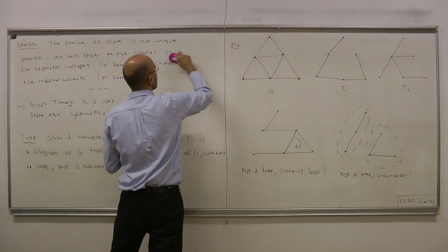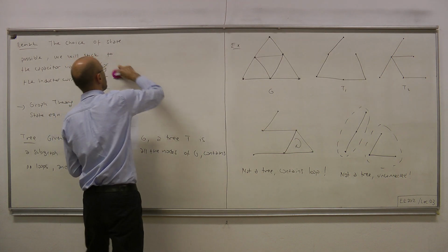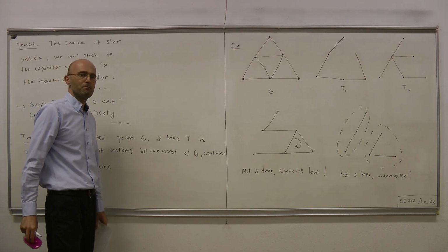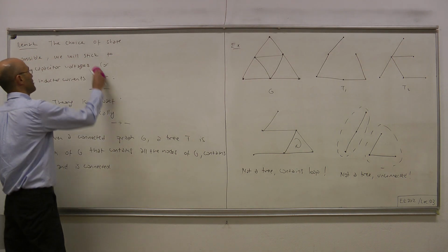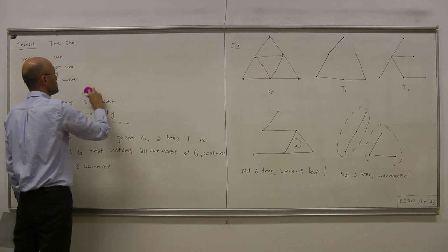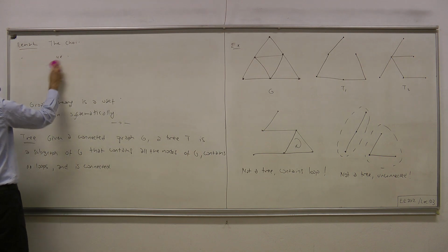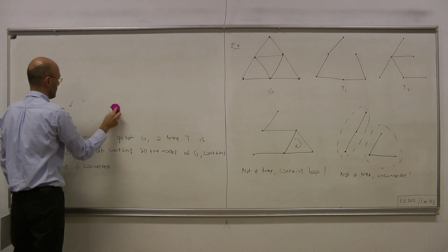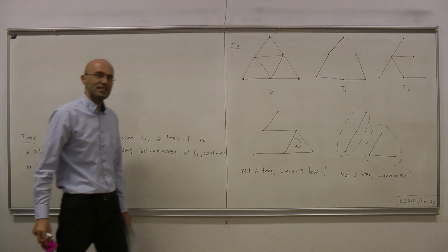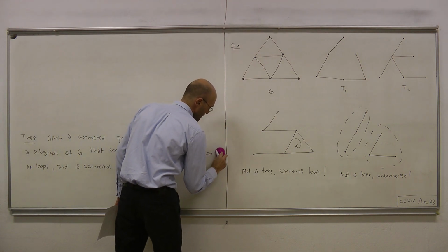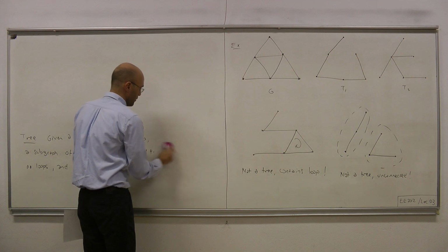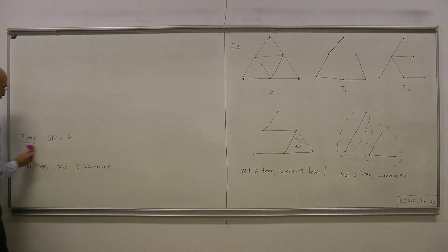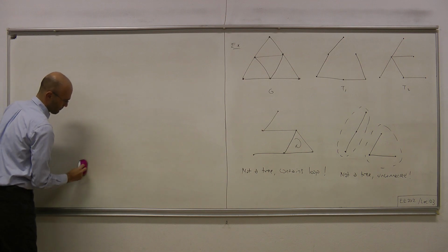Okay, and then using tree and cotree, we will be defining fundamental cutsets and fundamental loops, and defining those concepts will be very useful when writing KCL and KVL equations. And writing those equations will be useful in obtaining eventually the state equation.